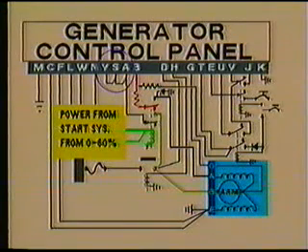With the B connection broken, the power needed to operate the electronics inside the control panel has been removed, making the entire generator inactive. It is the power provided through the B lead that makes the generator system a self-excited, self-powered system. An additional important reason for disconnecting the A lead and B lead circuits during engine start is to prevent damaging voltages from entering the internal circuitry of the control panel.